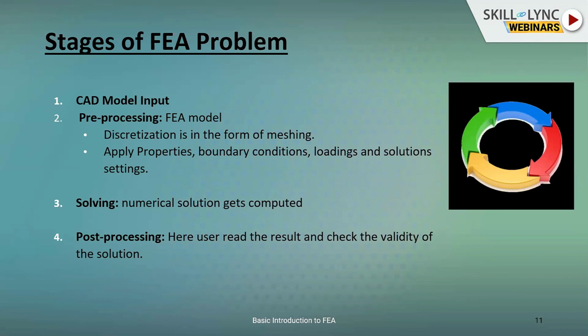There you have to specify the load step, the step where you define what type of analysis you want to do and what output you are interested in. All that data you provide there. Then we go for the solution, where the software actually runs the program at the back end and tries to solve all those partial differential equations and gives you the result for the entire domain in the form of displacement, stresses, and strain.